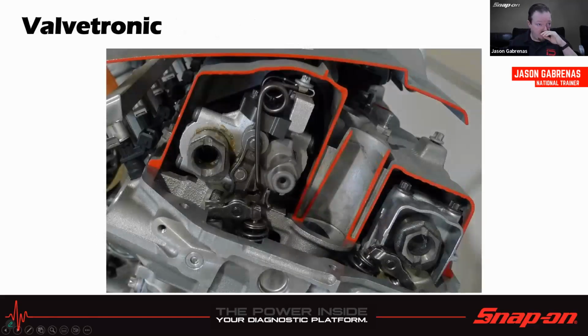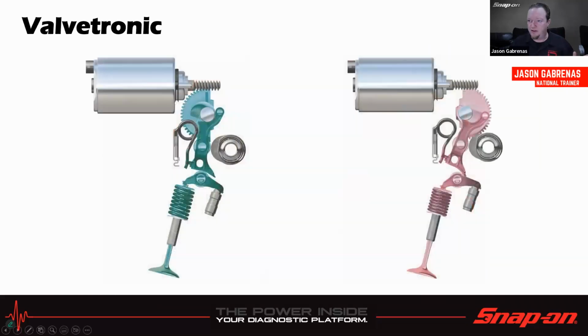All right, now let's move on to electronically controlled variable valve lift, which would be BMW's Valvetronic system that they use. So that uses some solenoids that change the profile of the rocker, and that works in a similar fashion, right? So we have these little solenoids here, and you can see how we have the rocker kind of shifted down like that. The camshaft pushes over here, so this is an eccentric.